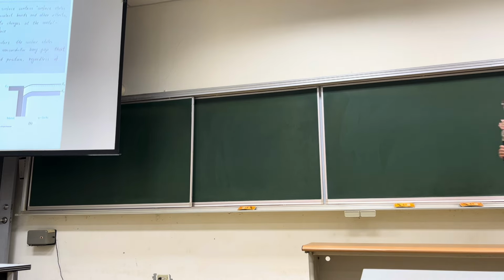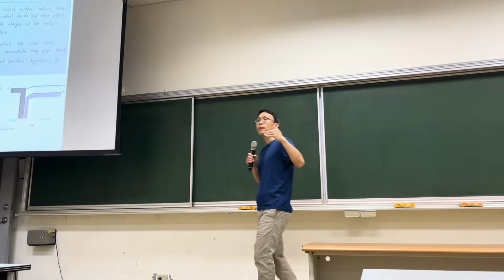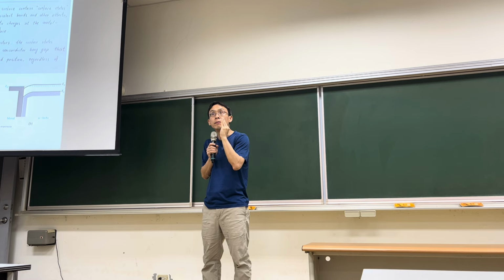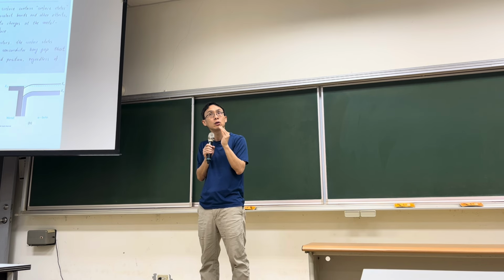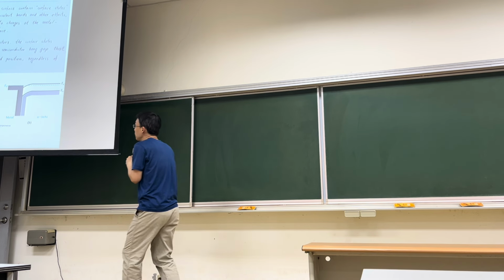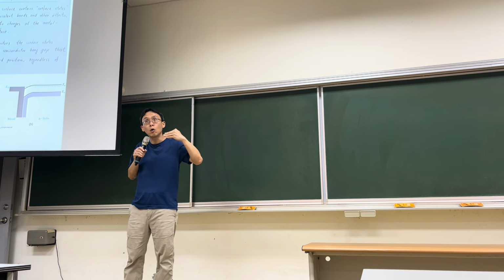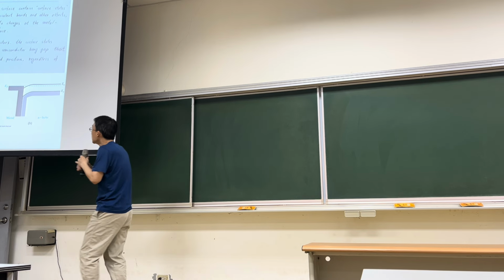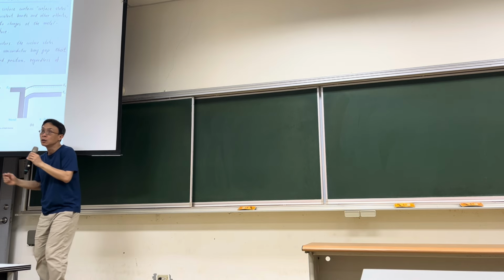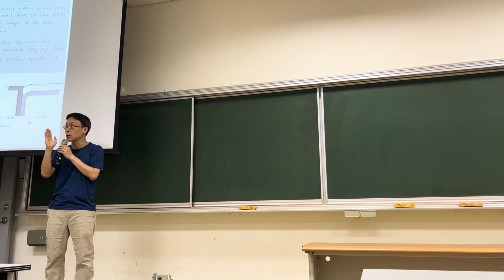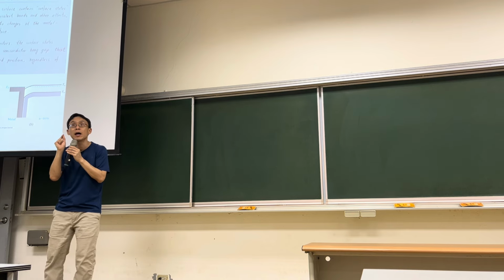And on the side of a semiconductor, usually you will have some very special phenomenon, which is called Fermi level pinning, right? For example, it doesn't happen to all semiconductors, but for some special semiconductors like indium arsenide or gallium arsenide, you will find the Fermi level at the surface of the semiconductor is a fixed value.